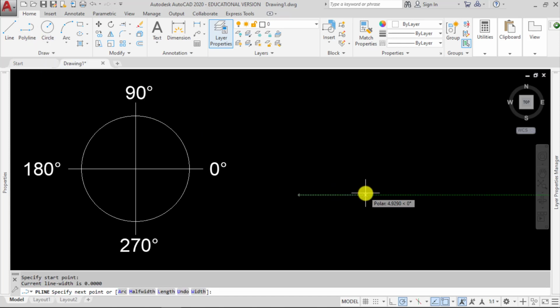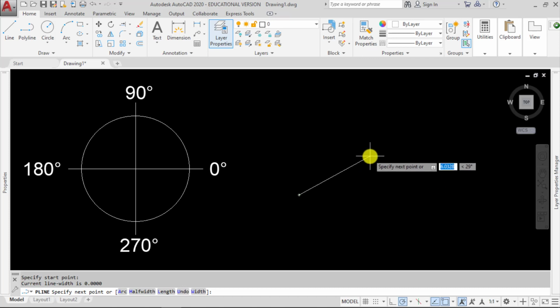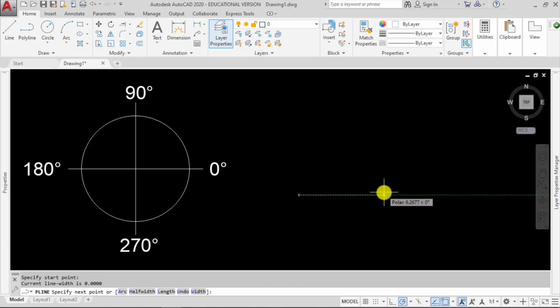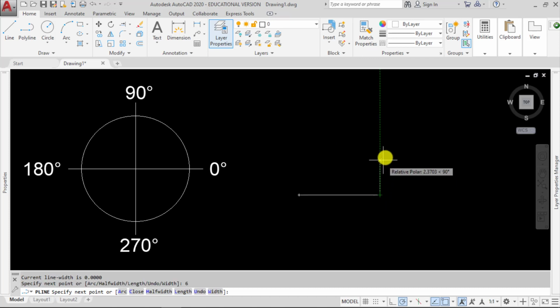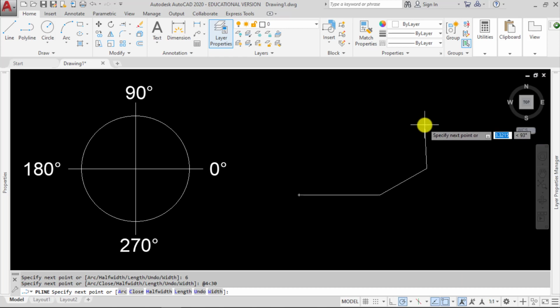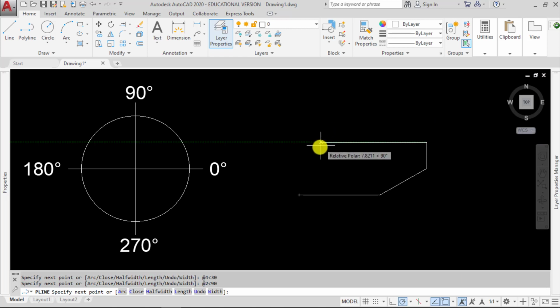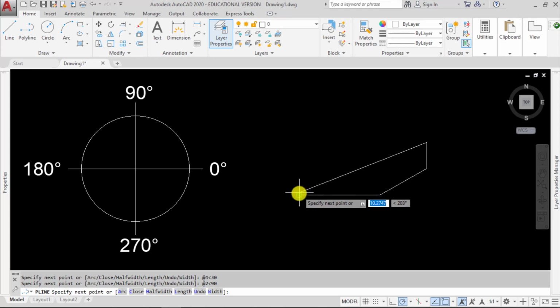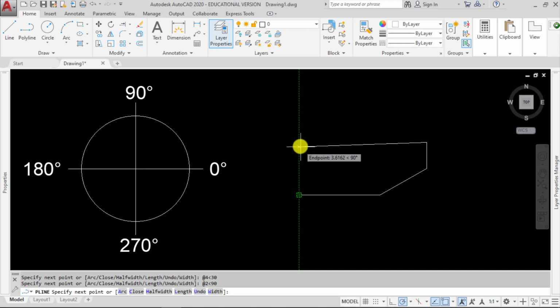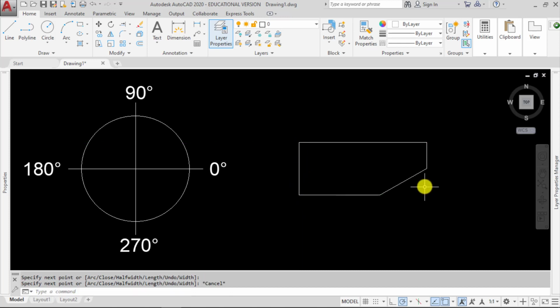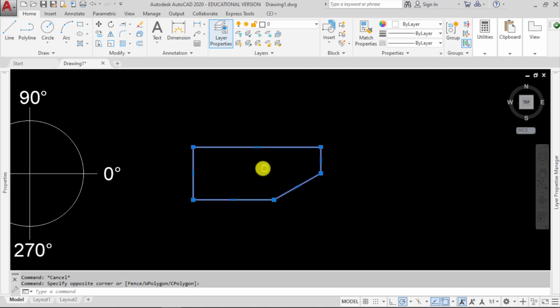So if we were to draw, they work the same way. If we were to draw this from an origin point wherever we would like, say 6 inches to the 0, let's go 30 degrees and a length of 4. Then we can go an angle of 90 and 2. Now the hover works the same way. So if I hover this endpoint, again, don't click, but hover, come up, and then let that click in and close my lines. Now I have one thing.